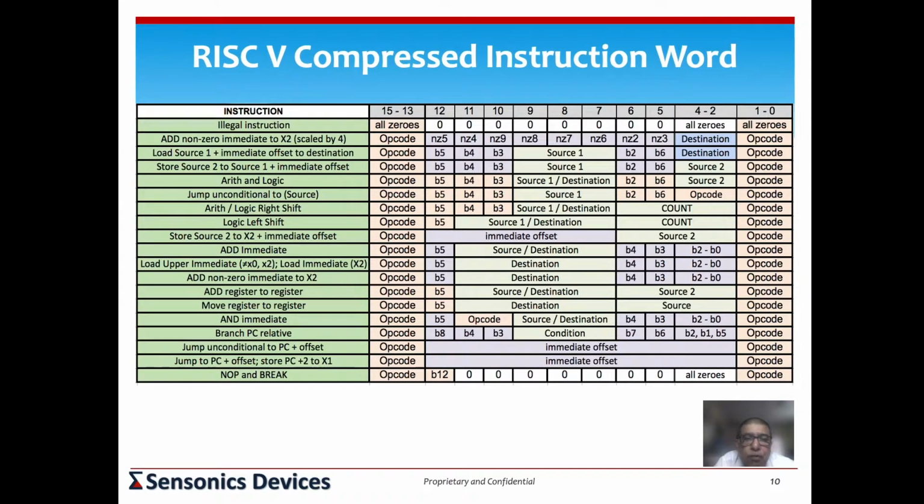Because there are some things presumed here, like you have these accumulator-based instructions in 8085. This is similar to that. There are some instructions that are R2-based, some instructions are R5 or R1 based, and so on. Those are implicit sources or implicit destinations. And there's a well-defined way, and it's completely combinatorial. There's no state machine to translate from one to the other. So you would translate this into a 32-bit instruction, shove it into the pipe, and it would execute as a 32-bit instruction.